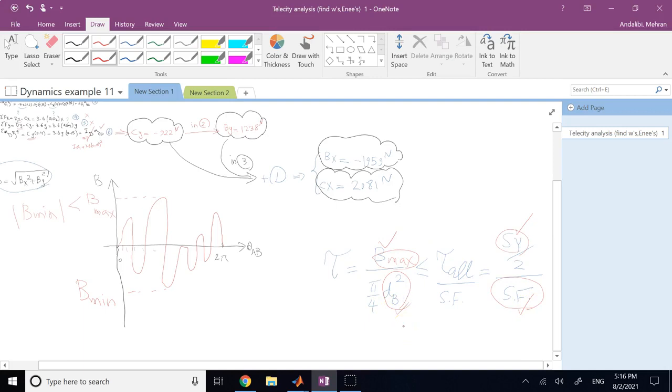A simple static analysis. The matter of fact is, when the material is subjected to a dynamic load like this, a phenomenon happens in the material called what? It's called fatigue. And when you want to design parameters for fatigue, the strength of the material is not simply going to be the yield strength, or half of that for the shear stress. This guy is going to go down.